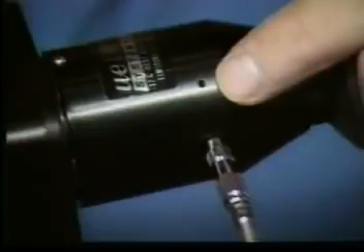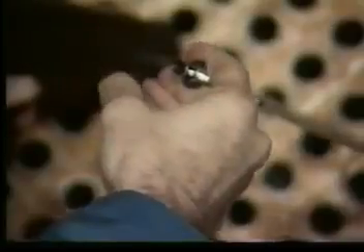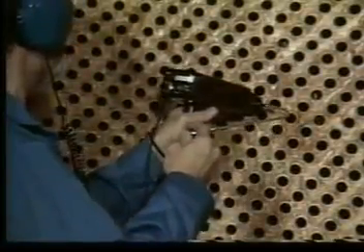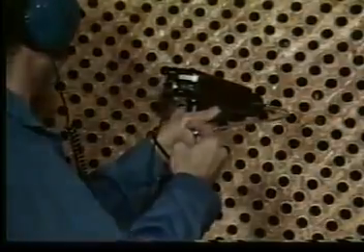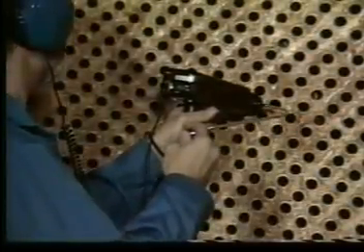At this point, we have effectively moved the vacuum flow from the tube to the hole by the vacuum leak confirmation module. Depress the plunger to seal the small hole near the scanning transducers. If there is a vacuum leak, the meter will drop. In the case of steam impingement, the meter stays the same.